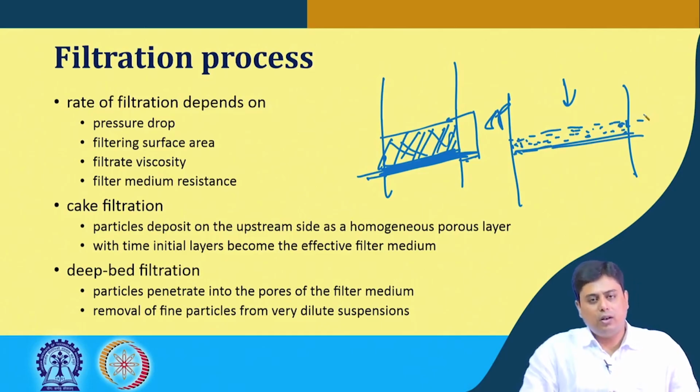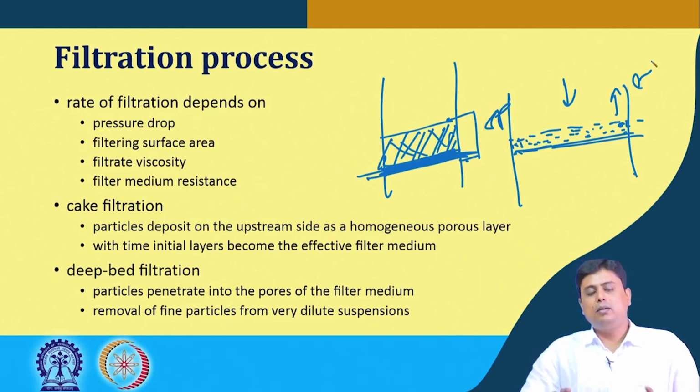The resistances in all directions of this cake or this thickness of porous media are uniform, and then this thickness builds up with time, and with time this layer becomes the effective filter medium. So which means the resistance in the filtration in such cases increases with time.